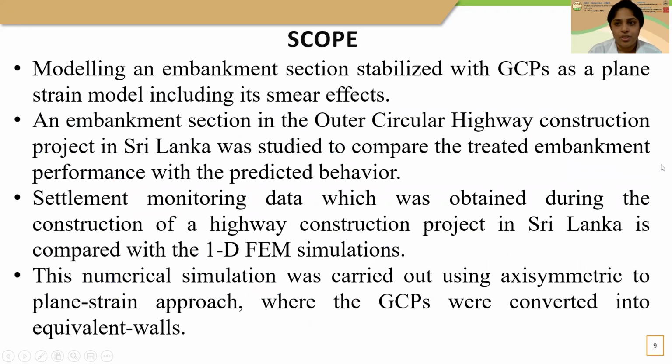If we are talking about this research, the scope of this research is to model an embankment section stabilized with GCPs as a plane strain model, including smear effects. For this study, we have selected an embankment section in the Outer Circular Highway construction project in Sri Lanka, and settlement monitoring data which was obtained during the construction of the highway project is compared with our finite element model simulation. This numerical simulation was carried out using an axisymmetric to plane strain approach, where the GCPs were